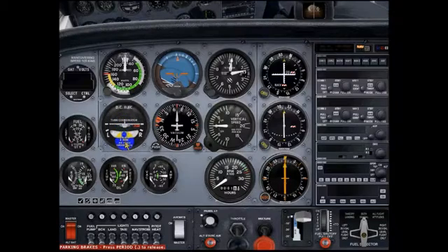Continuing, this is the turn coordinator. This is an indicator to the pilot when they're turning. It gives you the quality of the turn. Whenever you make turns, this ball should be centered. If it goes to the outside, then it's uncoordinated flight, and we call that a slip. If it's on the inside, it's skidding. Basically, if the ball goes to the outside, we want to step on the right rudder pedal, and I'll cover that in a minute.